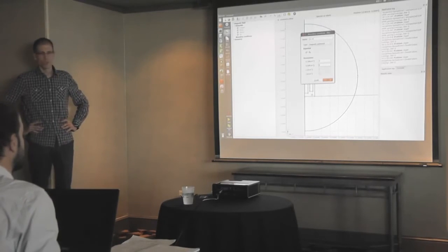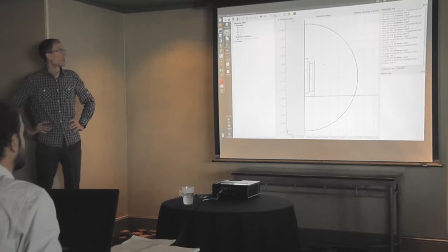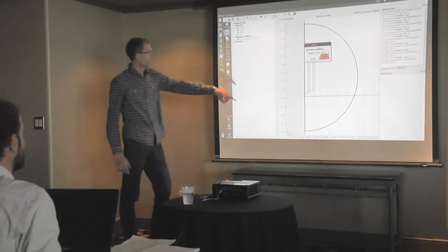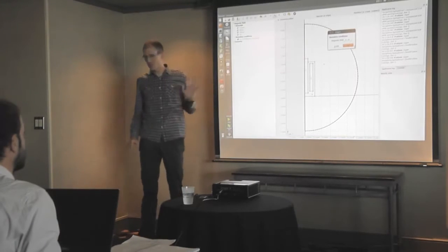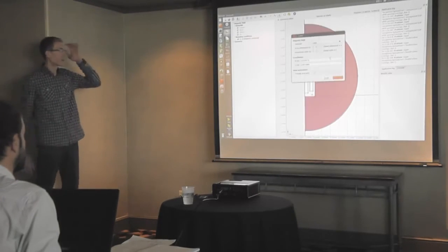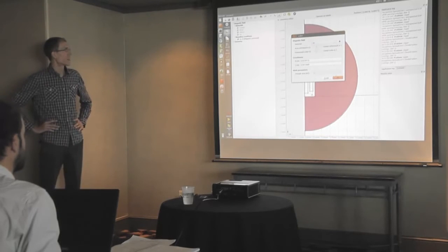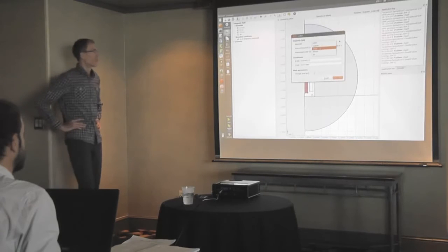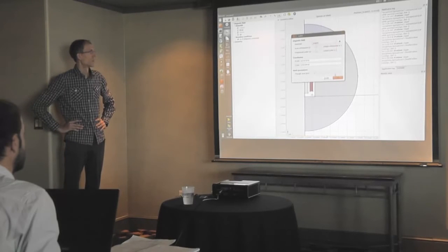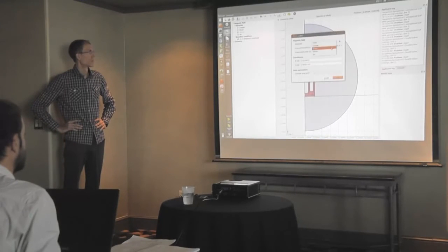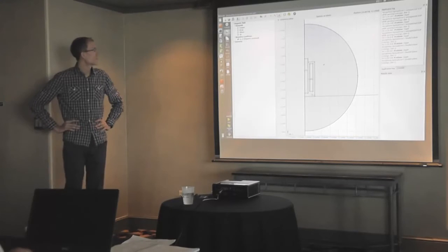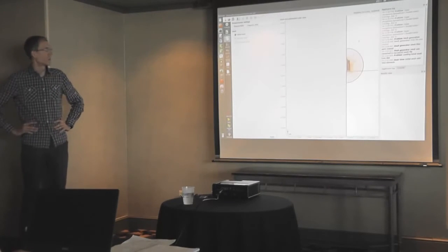For the magnetic field, we use just this simple condition, zero vector potential, which is both on the axis of symmetry and the fixture's outer boundary. So the boundaries are set, and now we assign materials to all the markers of the domain. Okay, so that's basically what we have to do for the magnetic calculation.